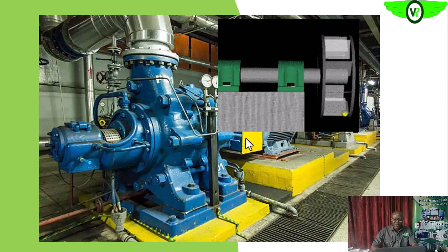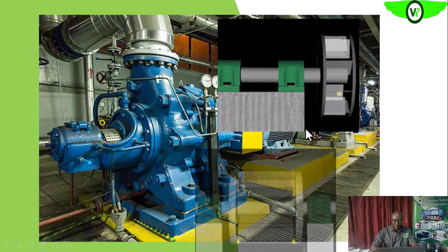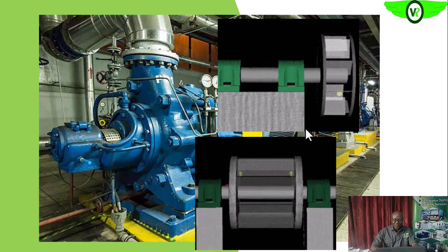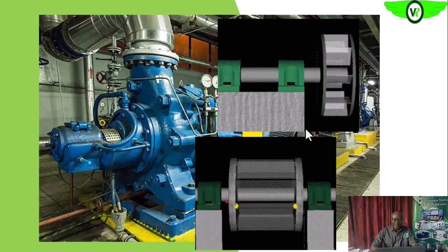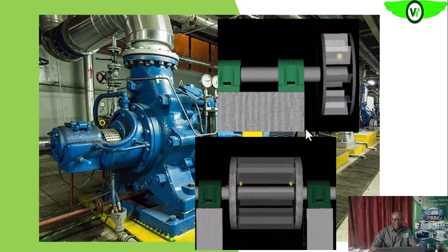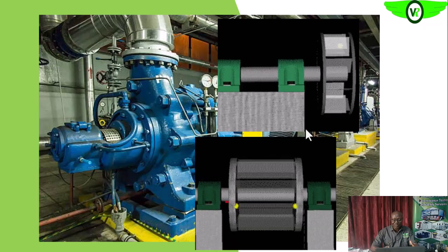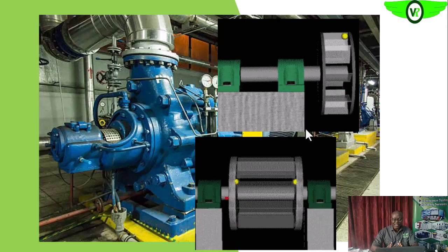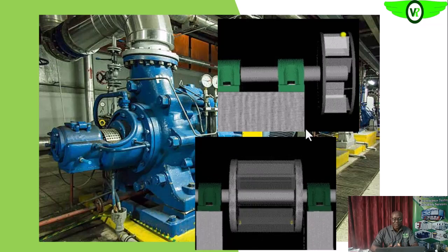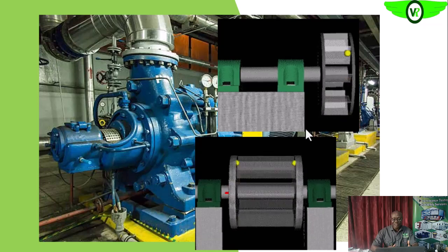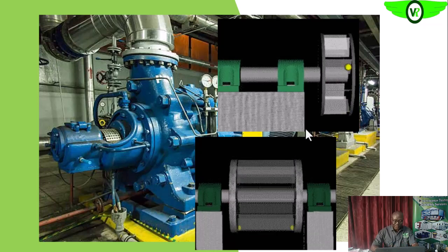So for this overhung fan, you see the effects of the unbalance. That unbalance is still a one-time RPM event. If you have multiple unbalances as you have here, once you resolve the summation of all of the unbalance forces, they'll be acting in a particular direction also. So you also have the one-time RPM events.